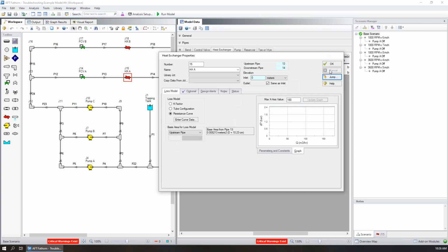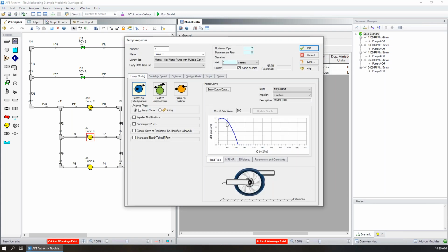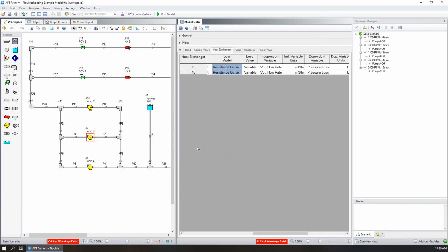The same thing goes for pump curves, where again, you want to make sure that it's seeing the same downward pattern, capturing this kind of first quadrant where it can operate on any point on this curve. You don't want to see an upward increase in DH over flow, because then the pump would essentially shake itself apart, be able to just add more and more head, creating more and more flow, and it would, I don't know what would happen. I don't think that could happen physically. So not a major concern.